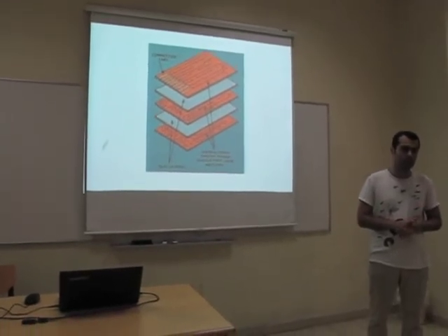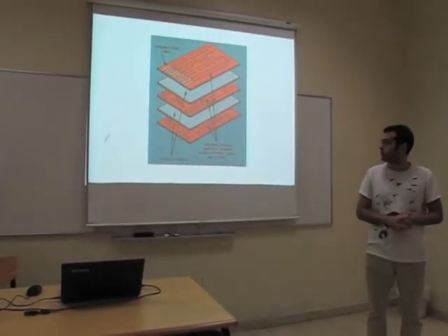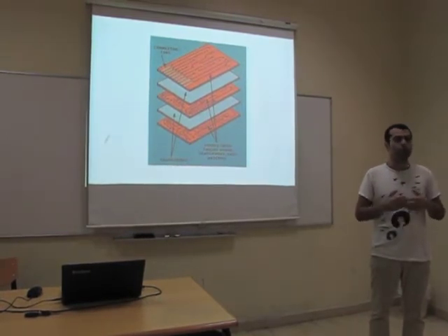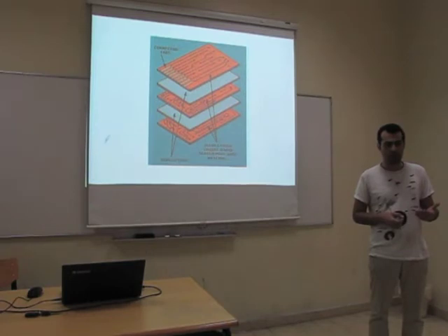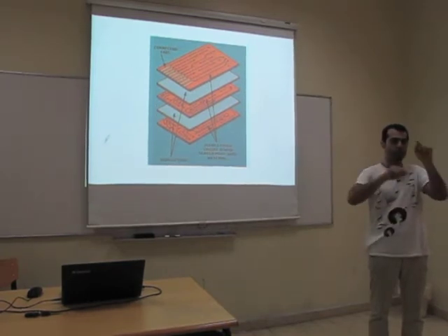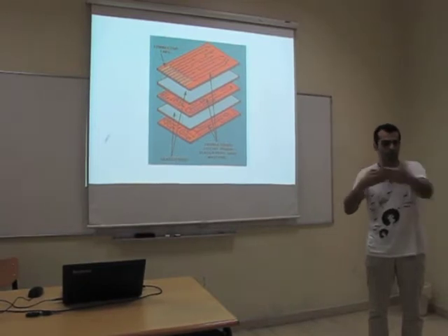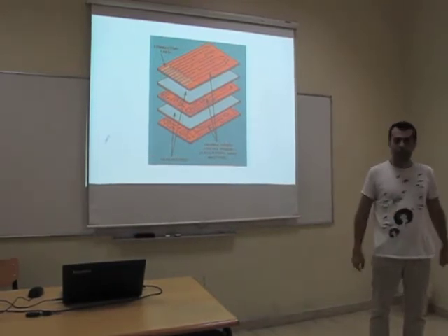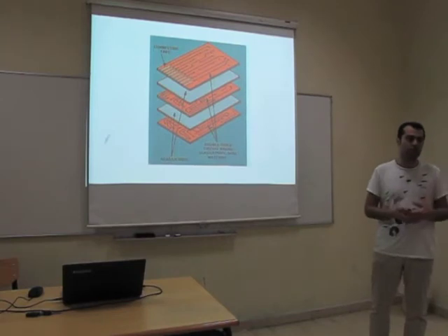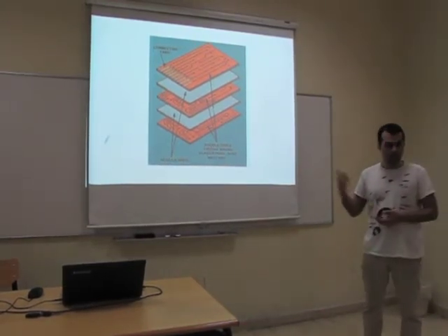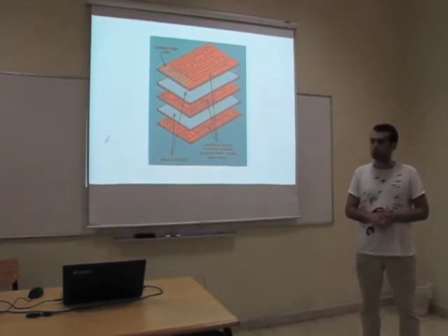What is the advantage of multiple layers? It gives you more flexibility to connect different things together. You are working on a 2D area. You cannot pass some of the signals. You don't want to short circuit them. So you need another path. Another path is not possible on the same surface. You need to go to another layer. You go up from underneath. And I'll show you on the software how we designed it and how it works. And we will build one in the lab today, and you will see how it works.